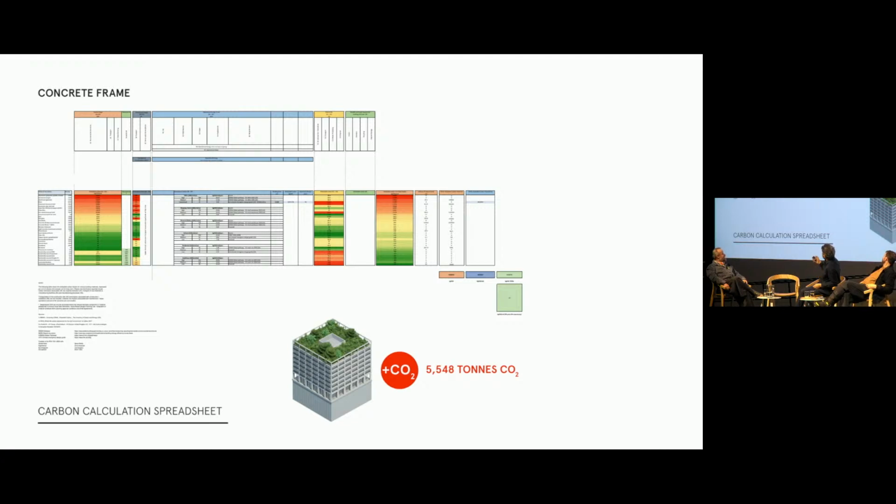So together we created this, just a couple of calculations on an Excel spreadsheet that you can plug the volume of materials you have in your design into, and it'll generate the embodied carbon of your building. And you use this as an iteration tool. Oh, I've gone over. Why have I gone over? Because I've used a steel frame. Can I substitute that steel frame with timber or stone? Yes, I can. What happens? Bang, it collapses. You keep doing that.